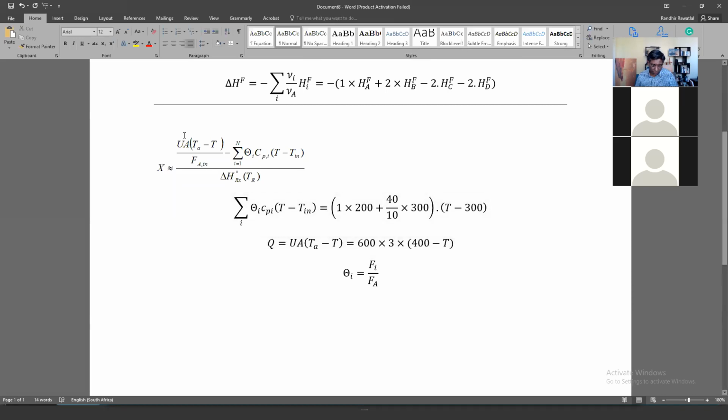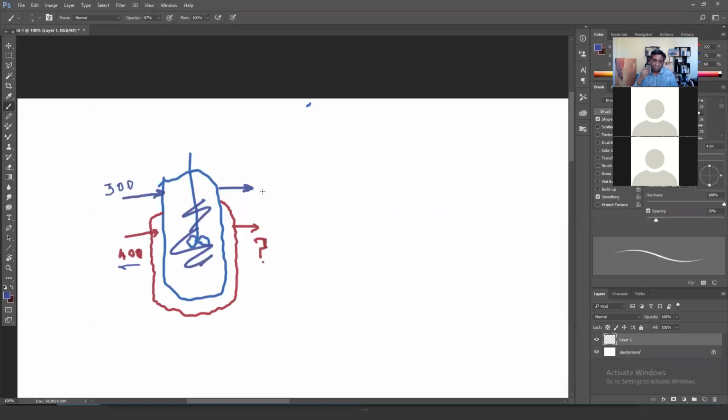And it looks like here we have gone and made the assumption that the flow is high enough, right? If you look back at that energy balance development, we are assuming here that the flow is high enough that you have the same temperature throughout this jacket. So imagine a jacket, it's like an annular space outside of your reactor.